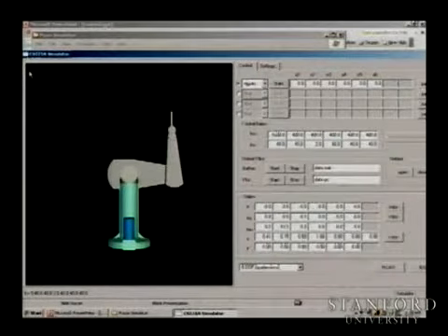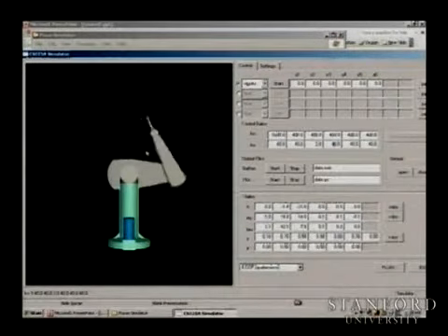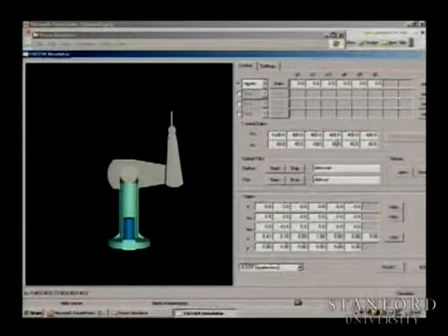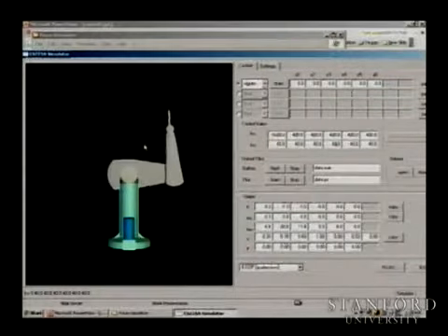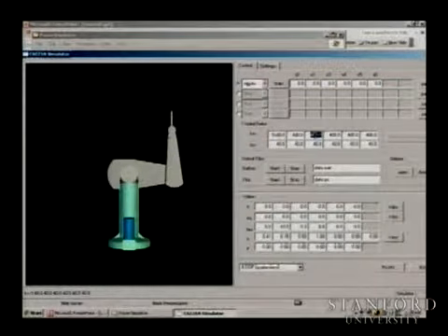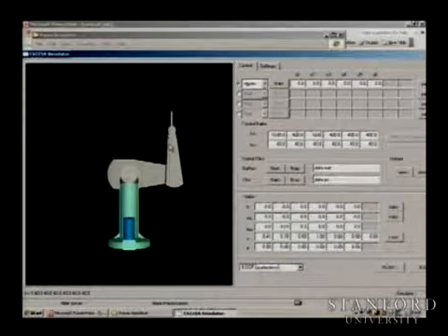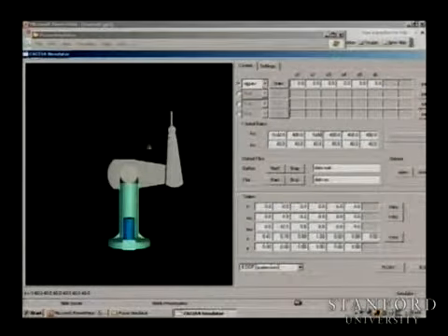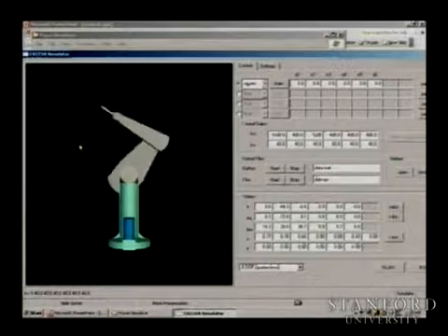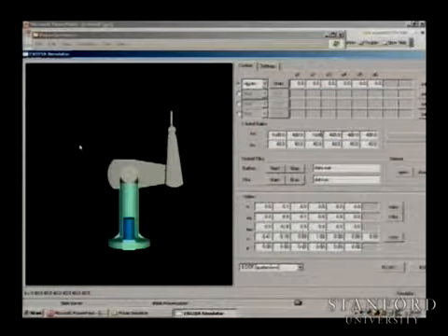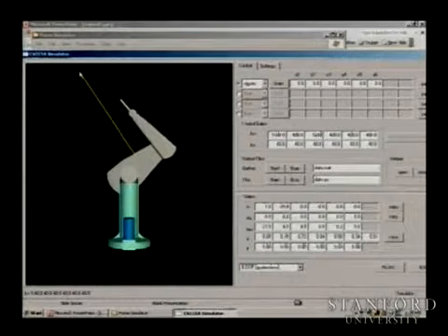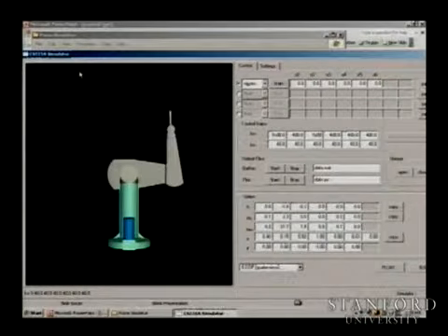So this is less? Yeah, it is less. Actually, you're moving a little faster, and you are still oscillating, and the oscillation is because we don't have enough damping here. So if we increase the damping, it will oscillate less. And if we increase the gain, do you see what is happening now? It's going very quickly to its position. So in fact, the coupling, this is the degree. You look at the 90 degrees between link 2 and link 3. It is maintained almost.